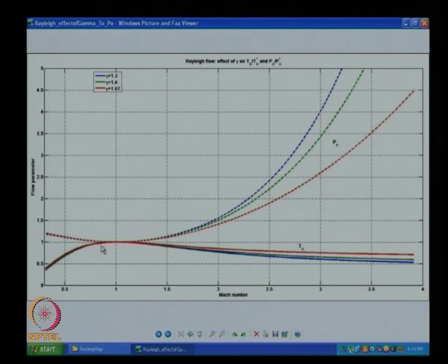This is the reason why the supersonic flow will suddenly take a subsonic path by going through a shock, and then it can handle a little more heat, okay, and it can still try and manage to get M equal to 1 at the exit without worrying about changing the flow completely. That is a possibility. This is very similar to what we did in friction flows. So, I am just telling you directly that there could be a shock sitting in your flow, and that can jump across to the other path and come from there to the subsonic solution.